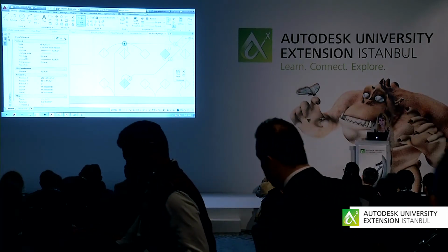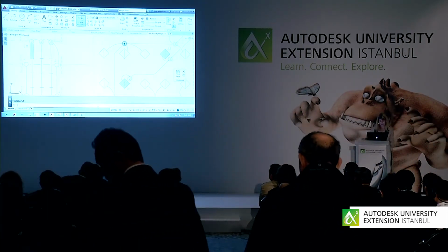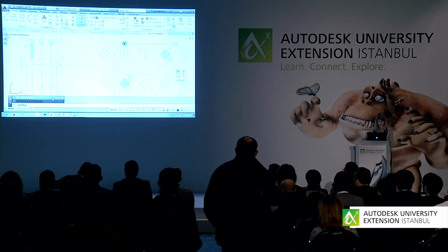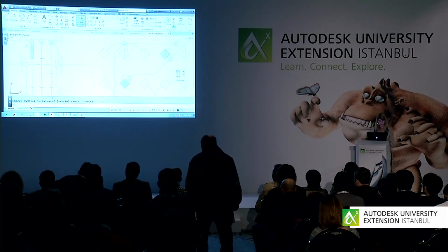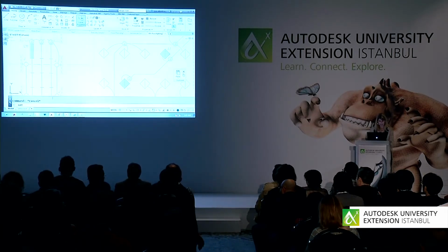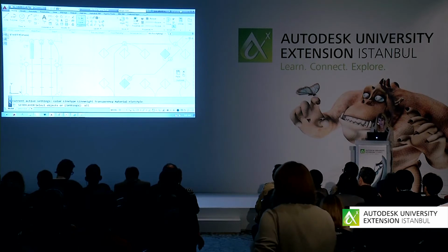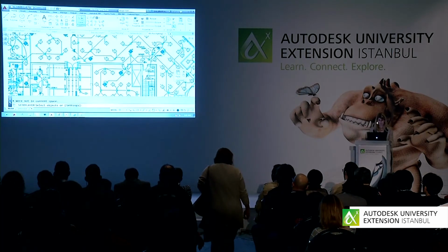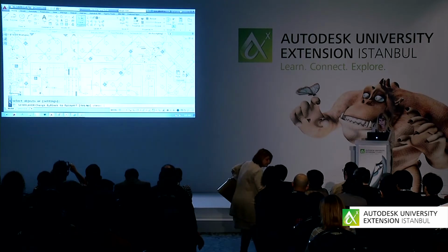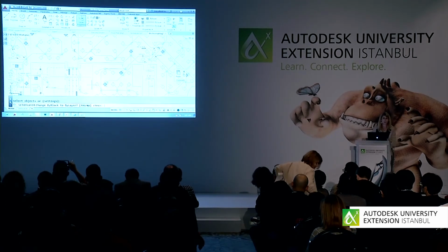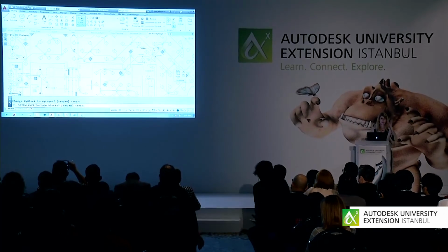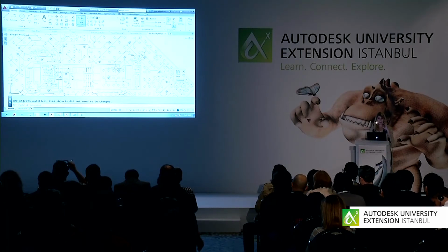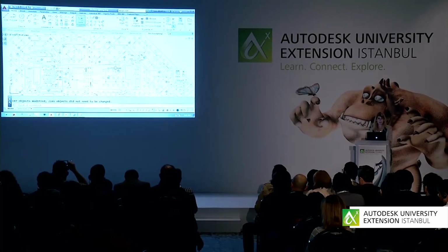So there's a fabulous command called setbylayer that will fix everything. Let's do it all. Let me make sure I can get everything. I'm going to say I want everything to be changed. So you can see everything is highlighted, right? Hit an extra enter. Do you want to change by block to by layer? Absolutely. Do you want to include the blocks? Absolutely. And now you'll see that everything in the drawing has been set to by layer. Much more efficient.